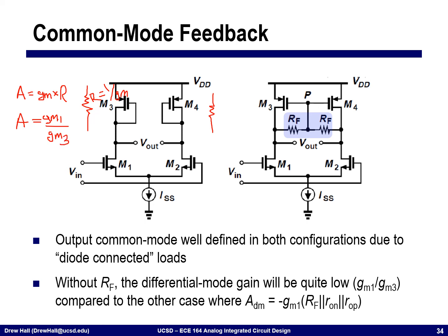Okay, so we've seen this circuit many times. We say that the circuit is ratiometric in the sense that depending on how I ratio the size of these 2 transistors, I can get gain. But I can't get a lot of gain. 20 dB is pretty difficult with this structure, and certainly not much more than that.